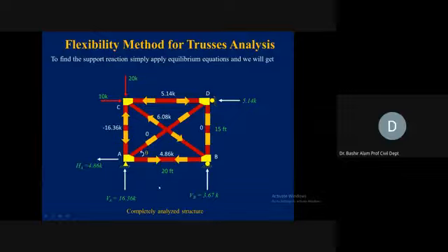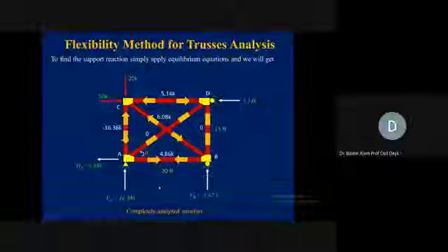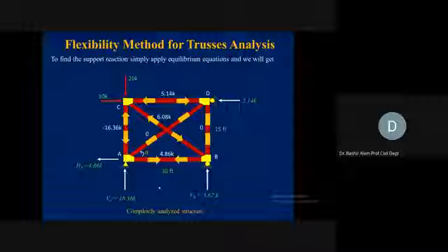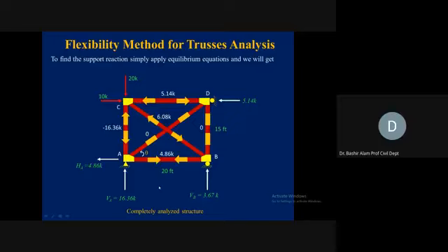So you need to pick the corresponding value for ASL from the capital P values, and the corresponding AMR will become ASR actually. Instead of the member forces, it will be the support actions now.